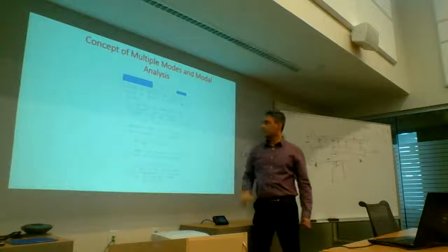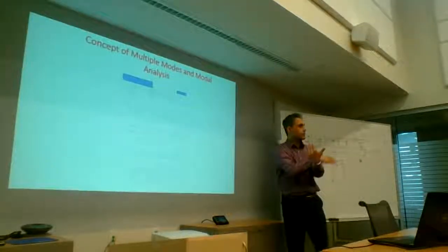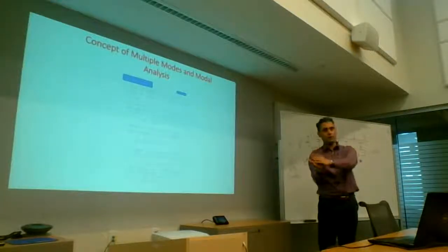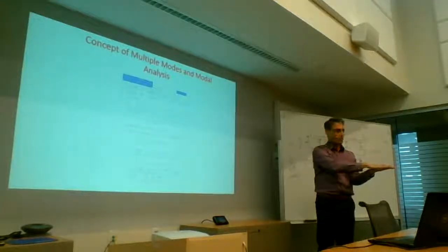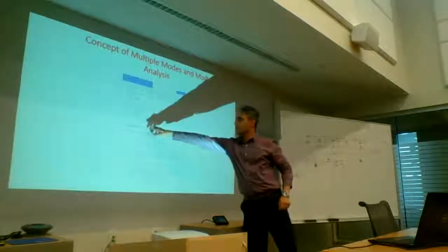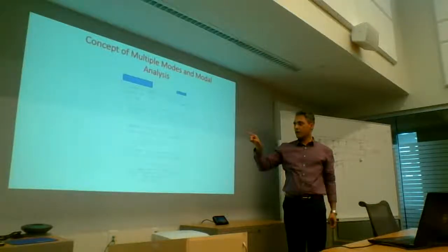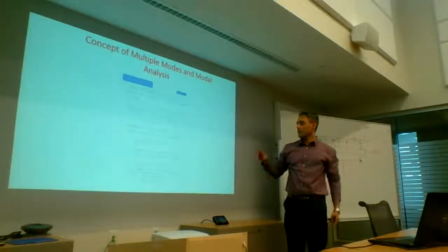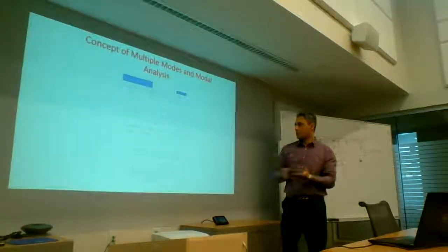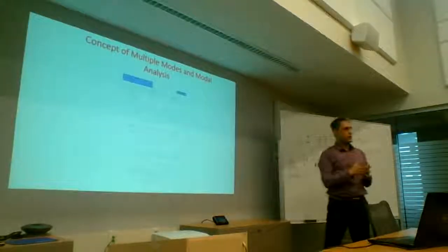And once you've solved the Qn, which is in the modal coordinates, you multiply it with the mode shape to get the actual displacement. This is now bringing it back to the original coordinate system. You transformed them to the modal coordinates, now you're bringing them back to the physical coordinates. Okay? So this U and T is basically at a given degree of freedom for a particular mode. And now to get the same thing from all the modes, you have to combine these together.